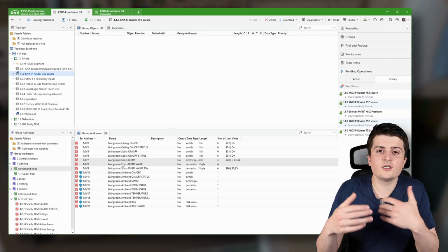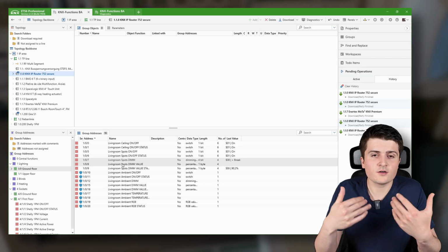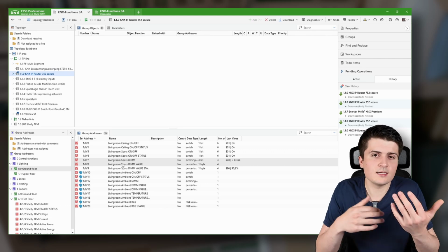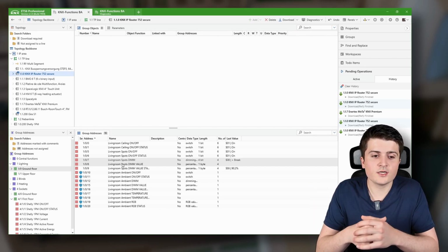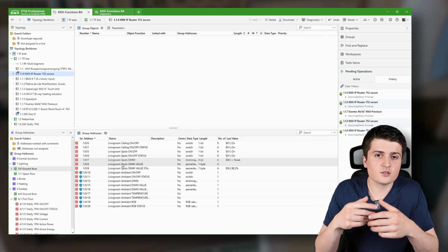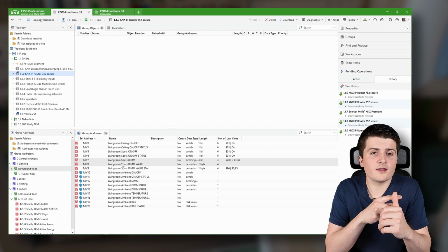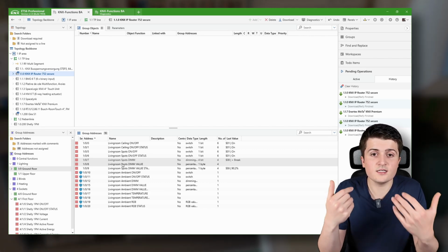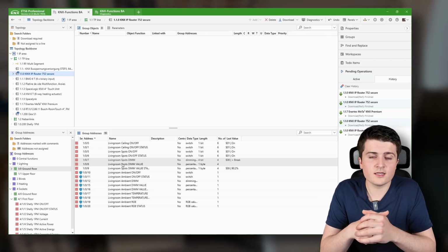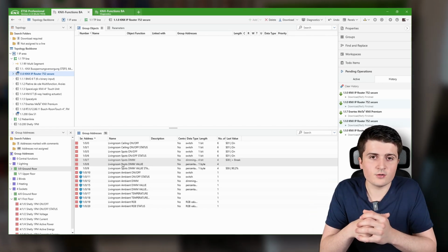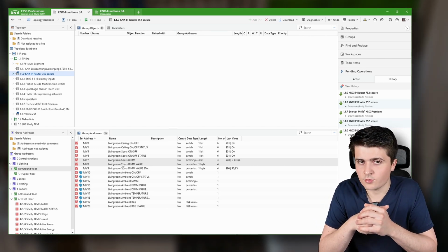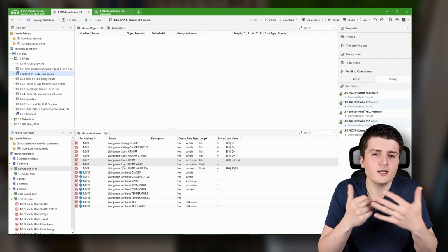Besides that, you also need to head over into the EDS and there configure a dummy device, which you can rename to Shelly, and you should also set it up to the same physical address. And then you can connect those dummy group objects to the group addresses the Shelly is using. So first of all, the purpose of this is that you will then see the Shelly device in the diagnostics and that the KNX IP routers in your installation also know about the Shelly device so that they will let those telegrams pass through. So from twisted pair to IP and vice versa.